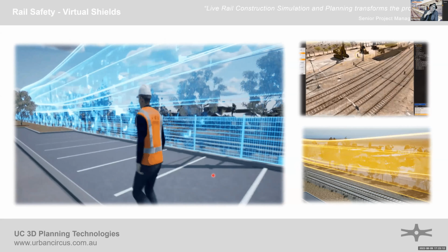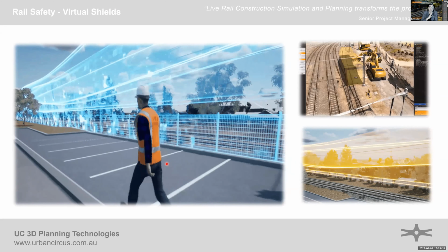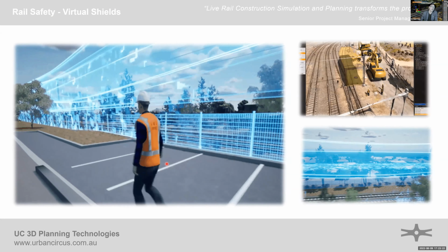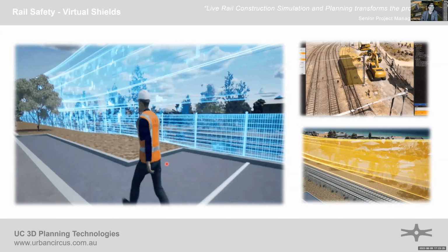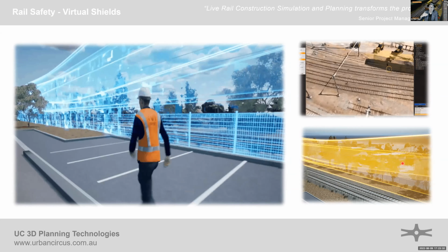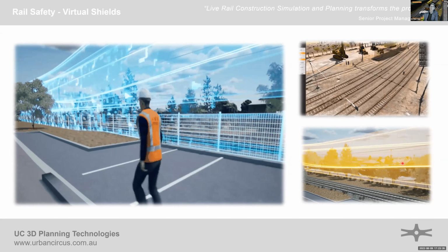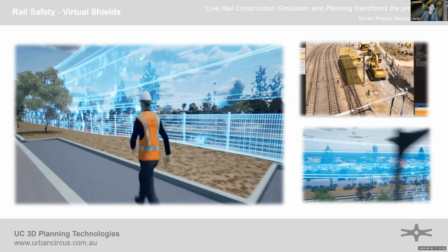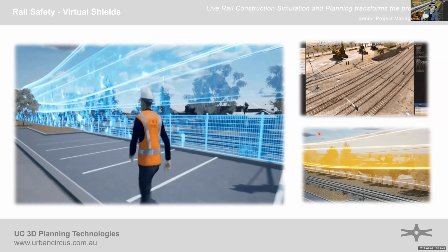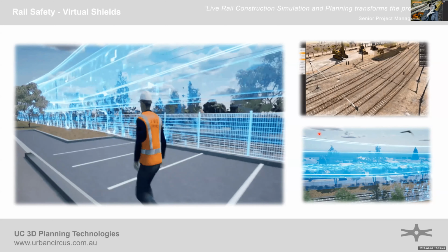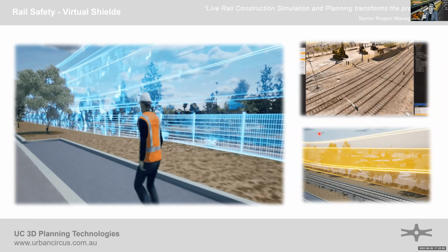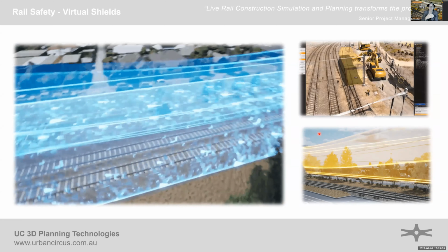So one of the next layers on top of this is you see the physical environment, but inside that physical environment are a whole bunch of invisible barriers, of course. There are a whole bunch of criteria. We're doing a lot of work in railway lines, as you can tell. So around the overhead wires here, sometimes people die. It's all too common, unfortunately, by using an elevated work platform going up, then they move into the electrified wiring system. So there are obviously safety zones around that, and there's a bunch of rules around how far you can get plant, like excavators, close to these overhead wires, and how far you can get humans. And some pieces of machinery have intelligent GPS positioning and control, so you can get them a little bit closer.